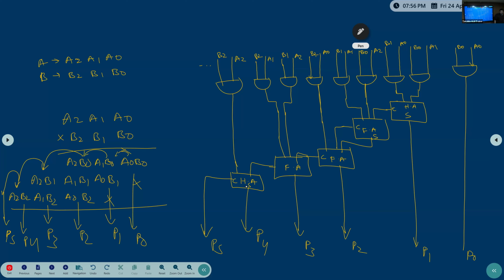Sorry? A 4 full adder will not be there, right? A 4 bit parallel adder, 4 bits will be there in that. Okay. But how can we use it here? There, how many bits are there? 4 bits. What will a 4 bit parallel adder do? It will add 2 numbers with 4 bits. Here we have only 3 bits, right? So no, 3 single bits we have.